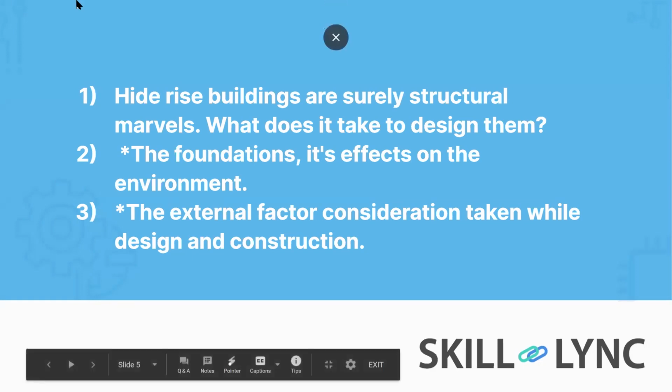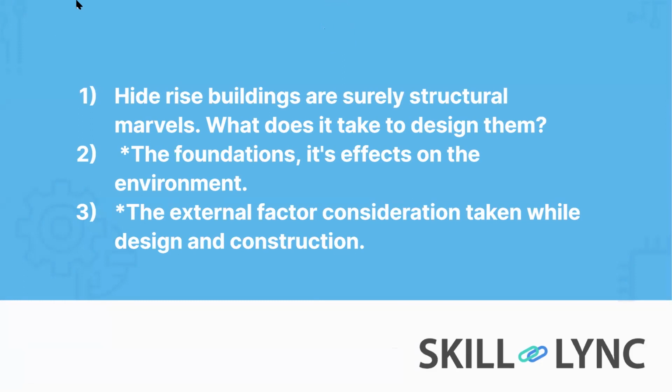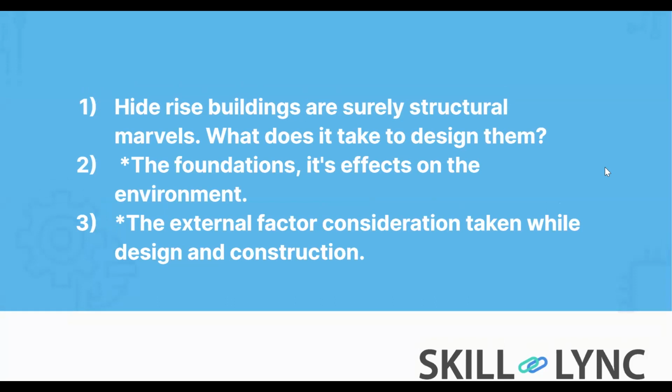So that is also a way to reduce the wind load. Or you can see some structures which have huge openings at the top of the building. So all these are ways how you mitigate the effect of the wind load, and that is the main concern or main challenge to be considered for design of a tall building or a high-rise building specifically. So that is one point.